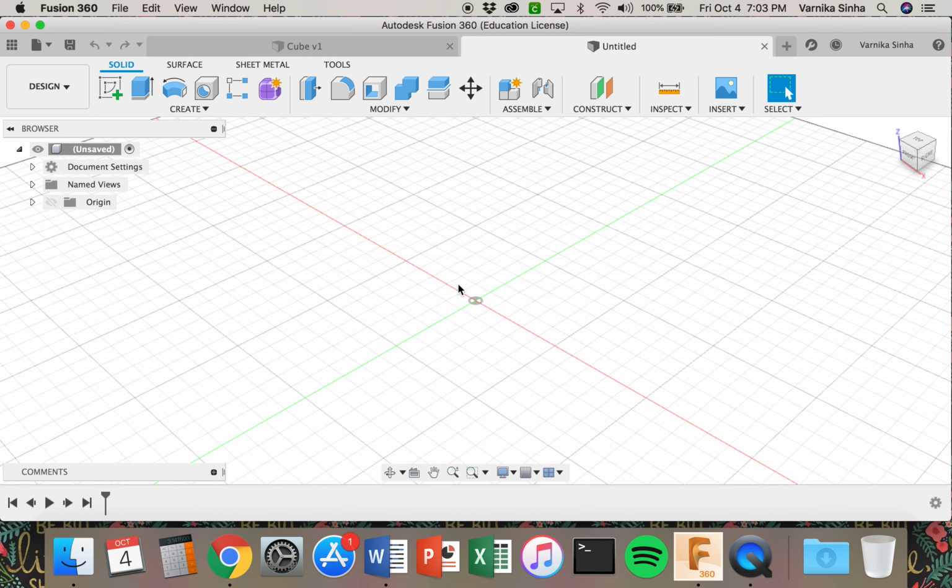It's linear. We can't alter the radii of the cross-section, which is what a circle is. So you can't be like, we have a smaller circle on the bottom and a bigger circle in the middle and then a smaller circle on the top. That's not going to work out because that's not how extrude works. Extrude keeps the same dimensions of the sketch from whenever you extrude it out. It will never change the dimensions of the original sketch. So then your question becomes, if I can't extrude it, how do I make a sphere? We make it by revolving it.